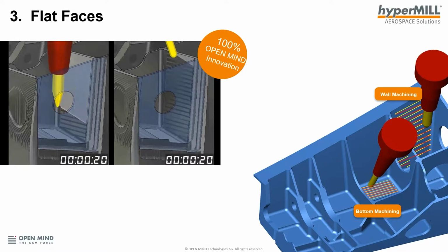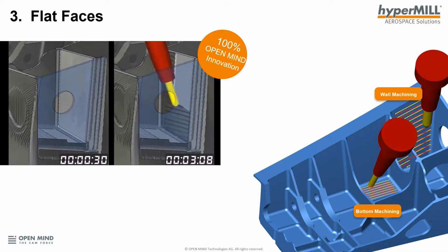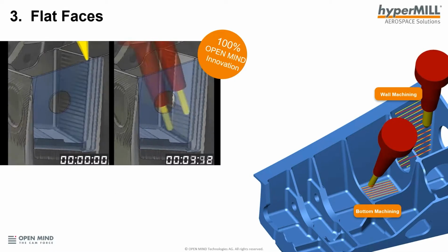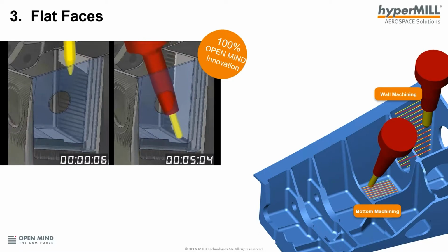If you don't do this, then obviously you are left with a very big wedge of material that's difficult to remove later. So this simultaneous motion is important. We then have a cleanup blending pass that goes around the outside to finish the toolpath off and to take out the small cusps. But this is a very dynamic motion on the part.